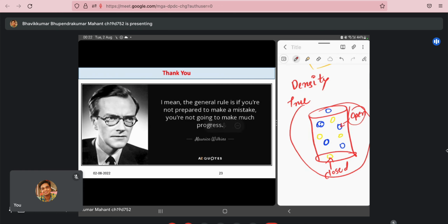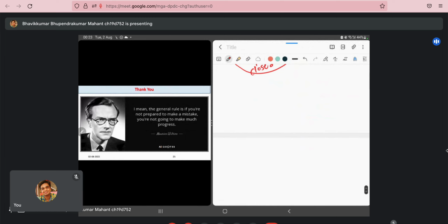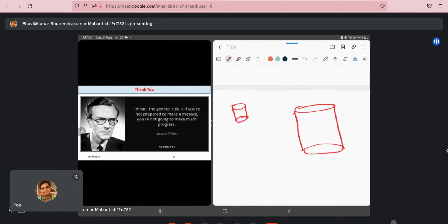Yeah, definitely, that is a very interesting question. Whenever we consider different shapes and sizes of particles, whether small or large, sphericity is considered for the shape of the particle. If I have a cylinder with this dimension, and another cylinder with very large dimensions, and I want to consider the sphericity, it is 6 Vp divided by Sp Dp.